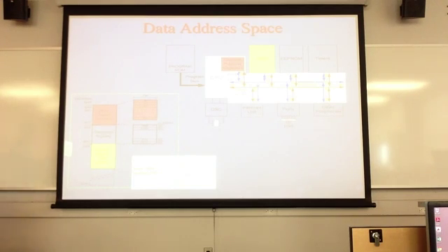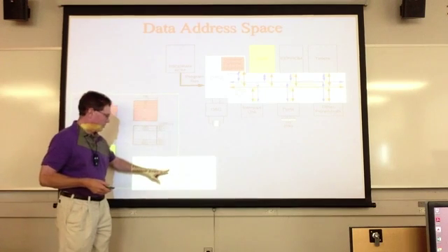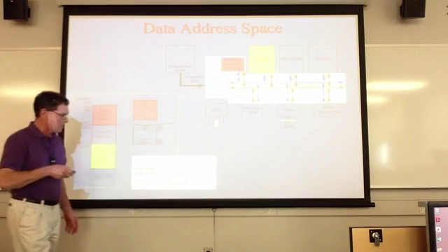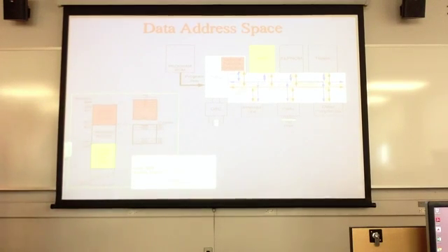So here I've got from the 169 manual that you asked about the other day. This is for the 169P, right out of figure 7.2 from the manual. Your data memory is comprised of, as Miles said so eloquently, 32 registers, IOs and SFRs, and then my internal RAM. When you're writing to internal RAM, you must start at location 0100 and work your way down to 4FF. That gives me 1K.